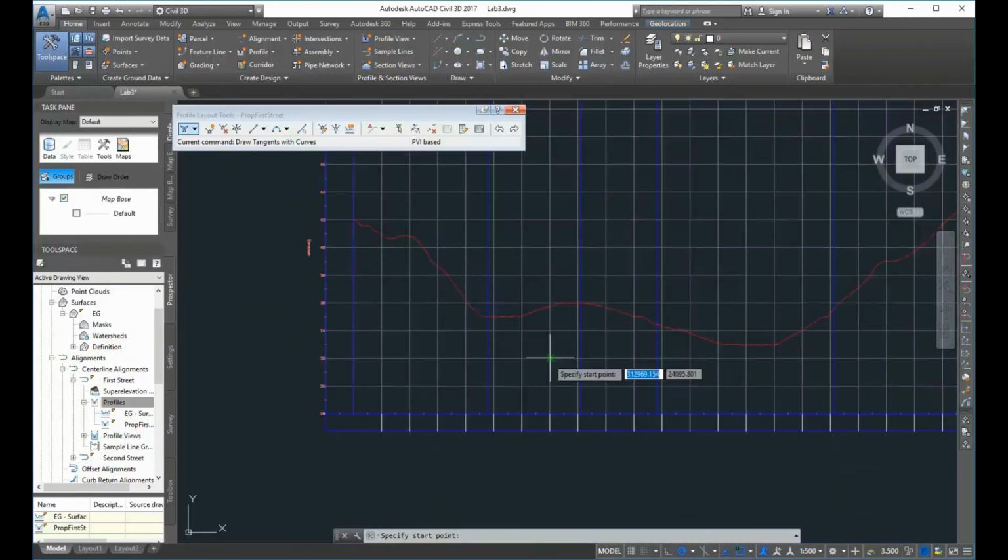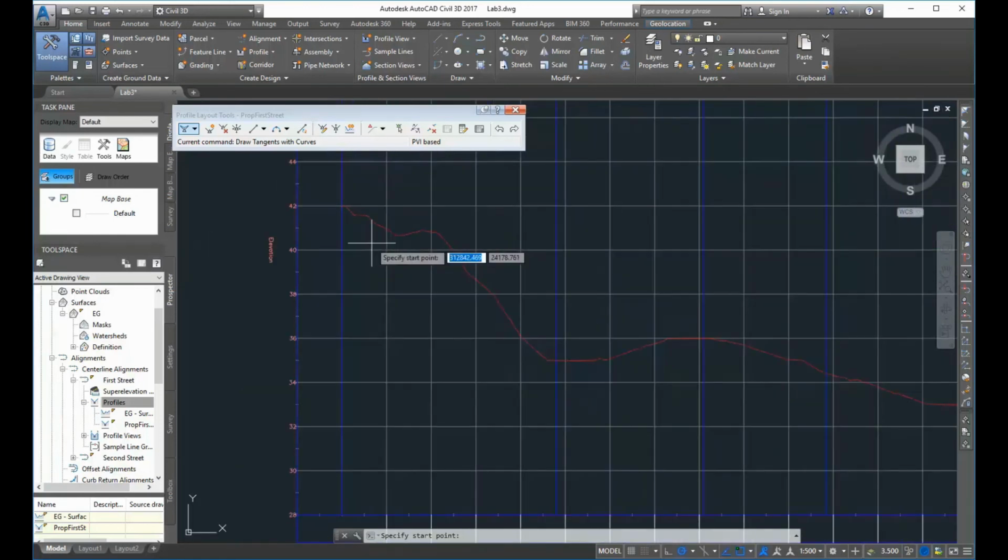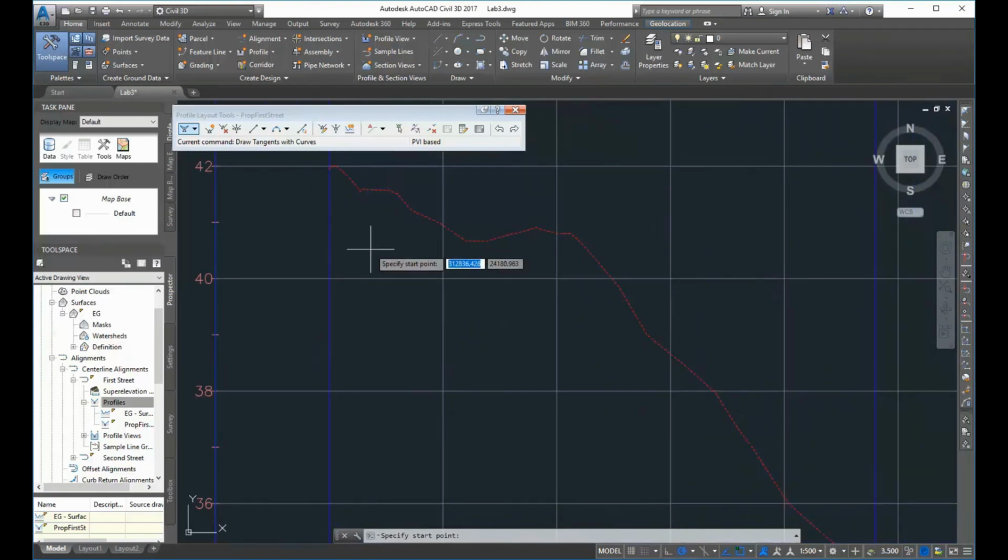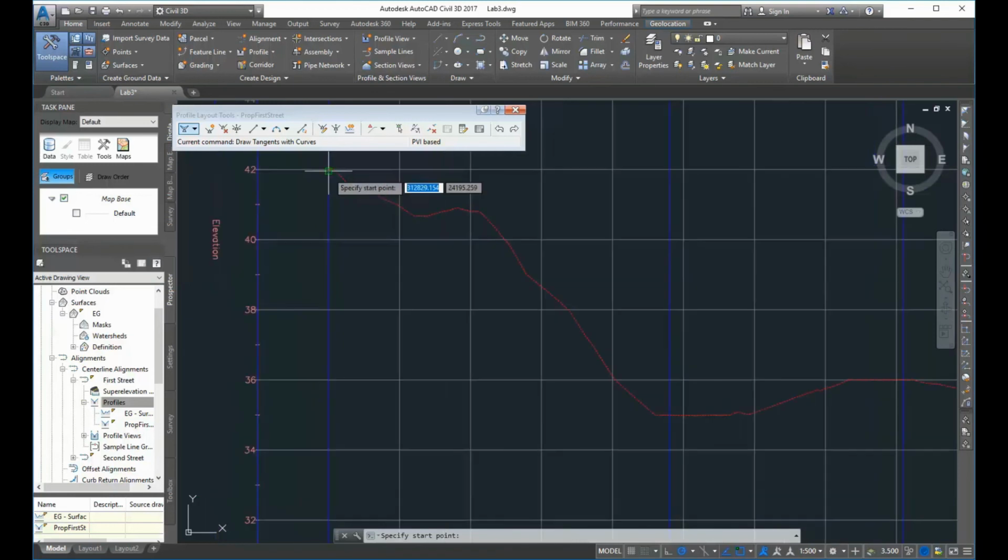So in most cases, when you think about roadway design, particularly in the U.S., we try to have really smooth surfaces so that our roads don't have a lot of topography changes, so that we try to hold our grades and have smooth transitional curves. And to do that, we wouldn't build the road exactly to the existing ground. If you think about roads that you drive, in some cases they're sort of built in or cut into the hillside. Other places they sort of stand above the surrounding ground and fill. So we're going to do the same thing with our proposed design.